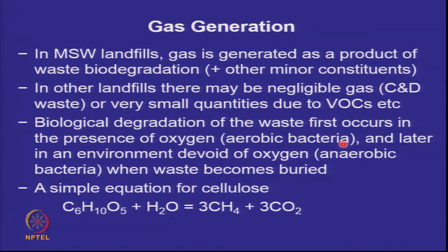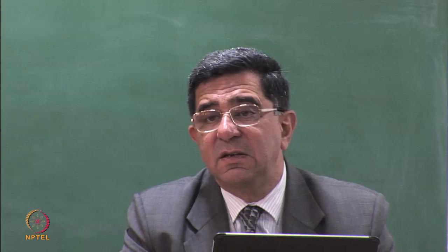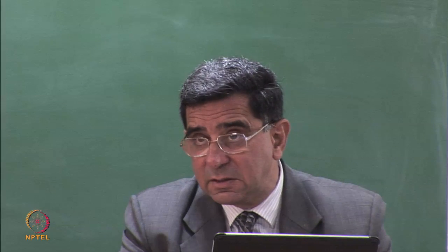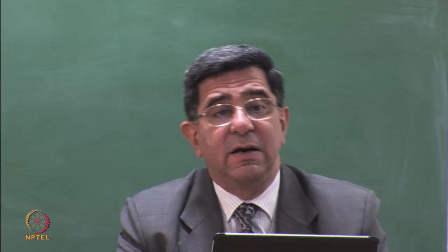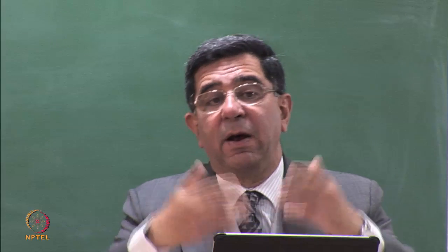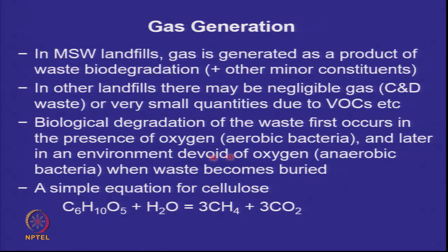But the waste fills up rapidly in a landfill. So once the initial oxygen is removed or utilized, then no more oxygen comes in, because you are putting a daily cover, a soil cover at the end of the day, and the waste gets buried. So later anaerobic bacteria take over and we have anaerobic degradation.